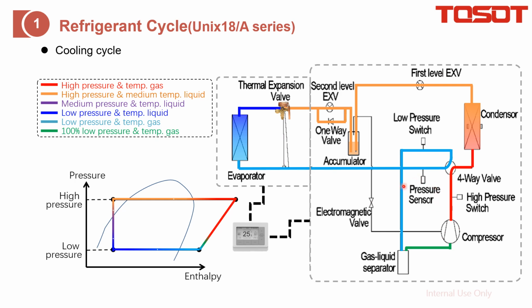And also just pay attention to this one, the pressure sensor here detects the low pressure, and also you will find that during cooling, this electromagnetic valve is fully closed because we don't apply the EVI in cooling mode. And also I put this pH diagram here just for your reference.